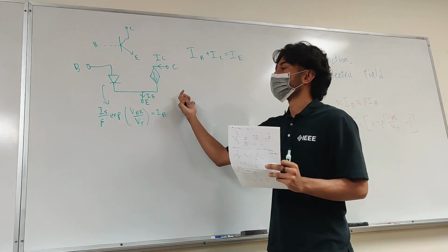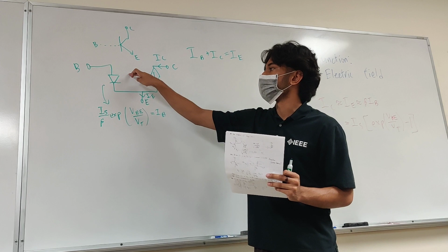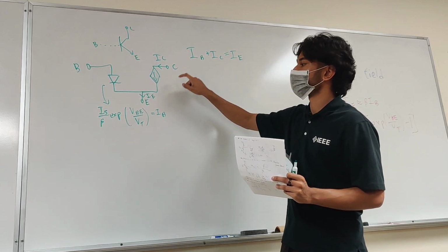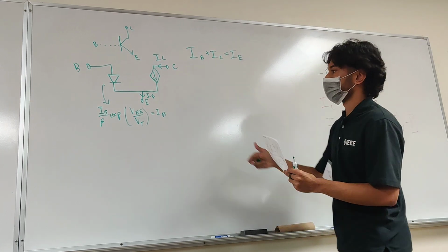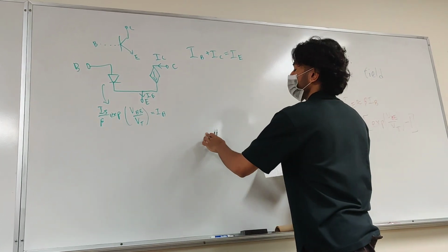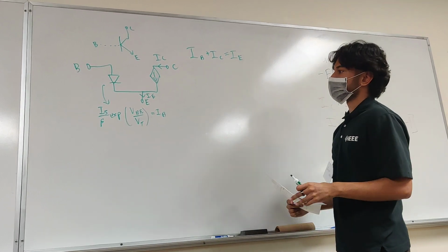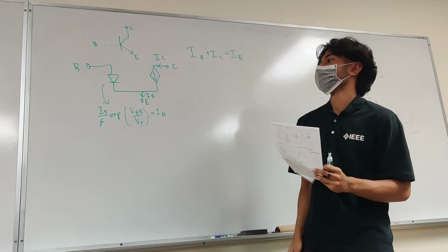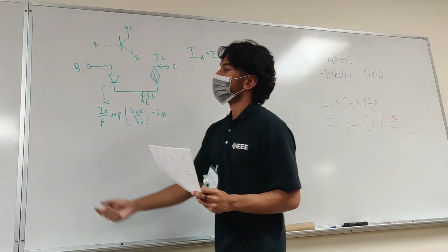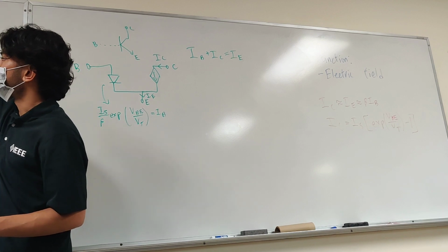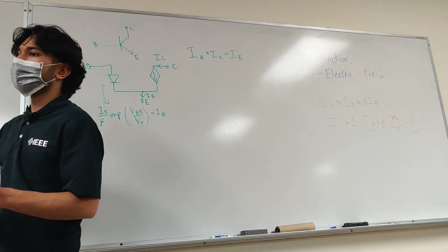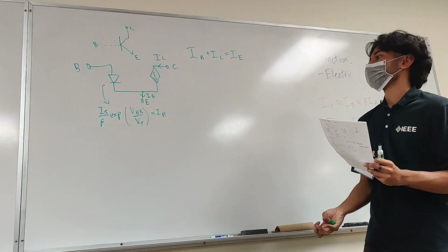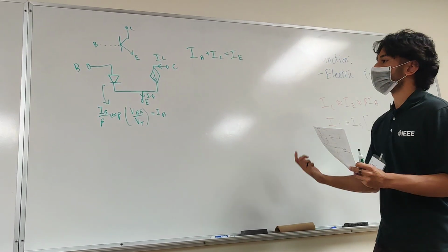This is what we look at, okay? There's a diode between the base and emitter, and there's a voltage-dependent current source between collector and emitter. Okay. And I guess the next thing we're going to talk about is what do we do to get gain out of our device? We've already covered how we apply a certain voltage and can change what current we have. That's the general idea of a transistor, right? Now, how do we get gain out of it? How do we amplify something?